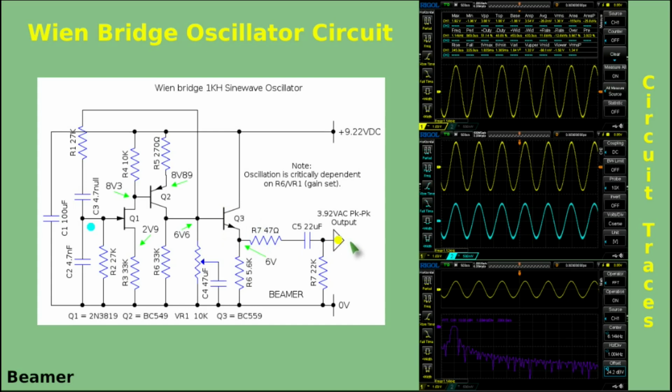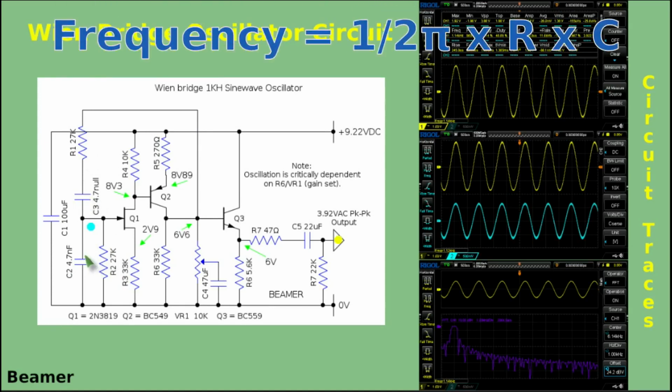This circuit is not a million miles away from the phase shift circuit I did earlier. Let's look at this circuit in finer detail, particularly the Wien Bridge, these 4 components here. Well, the first series components here, these 2, this resistor, this capacitor, is in series with the feedback loop from the transistors. And these 2 components, the R and C, are in parallel, and they represent another circuit. Both the resistors need to be identical, and both the capacitors need to be identical.